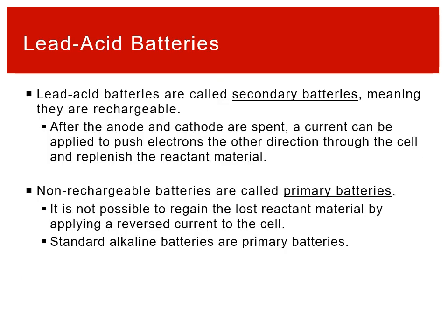Another major reason why we use lead-acid batteries in the context of, say, starting a car is because they're what are called secondary batteries, which is just a fancy way to say rechargeable. After the anode and the cathode react, you lose your reactants. What you can do is push electrons the opposite direction than the spontaneous direction, and you can make those original reactants come back. You can form whatever the initial reactants were.